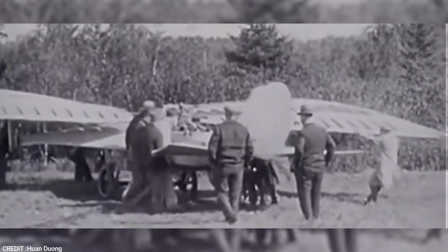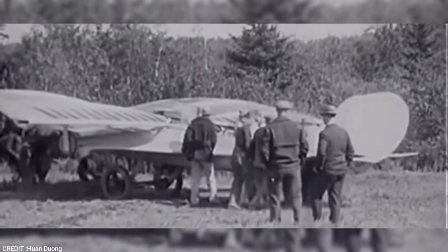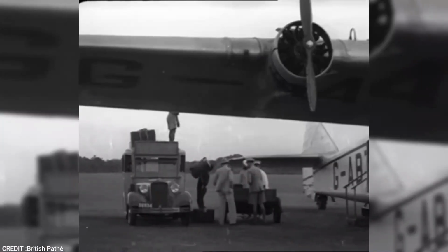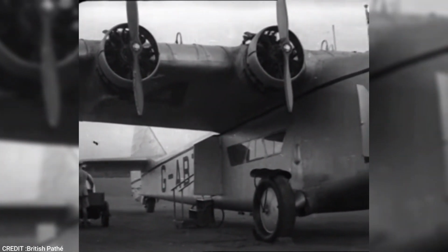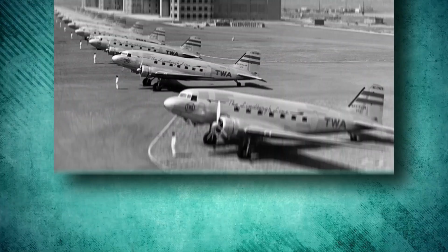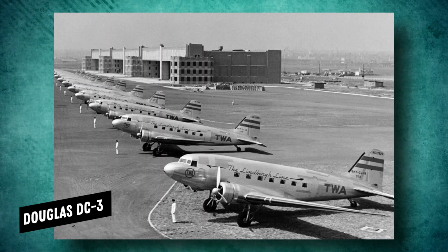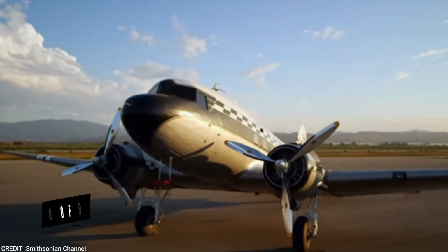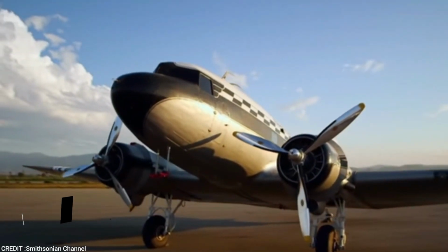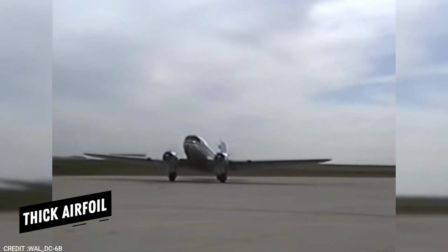In the 1920s, airplane designers moved towards the use of thick airfoils. By the 1930s, efficient wing design exhibited large aspect ratios and thick airfoils. The famous Douglas DC-3 is an excellent example, with its aesthetically beautiful high wing aspect ratio of 9.14 and streamlined 15% thick airfoil.